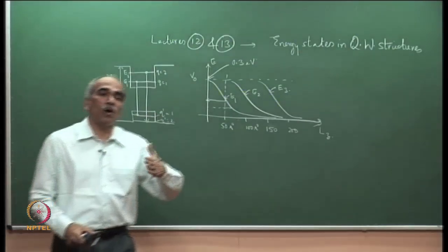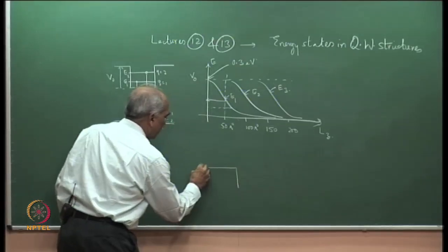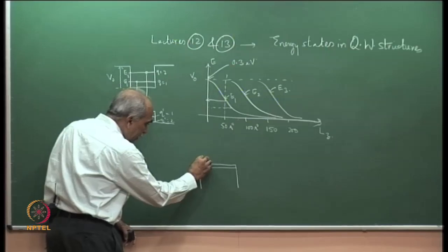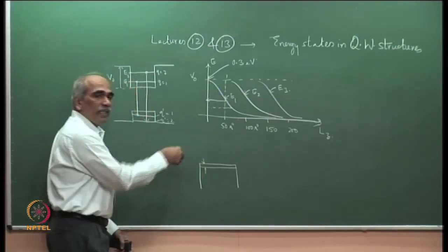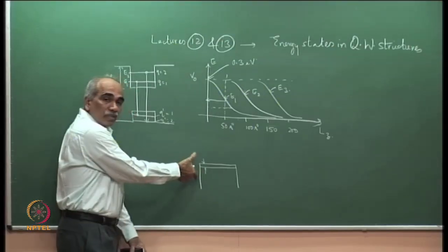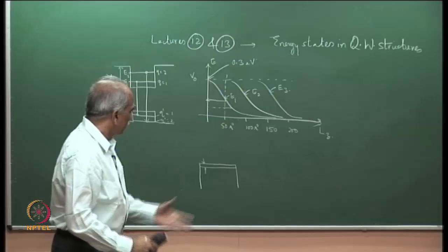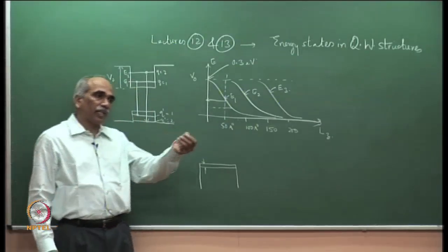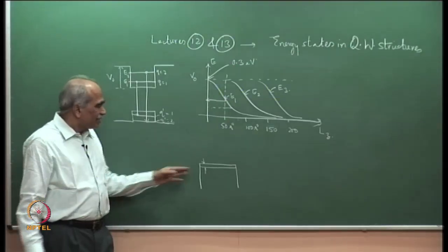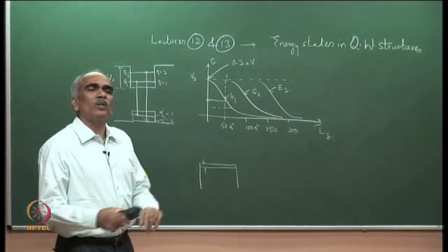If you are depositing a layer by epitaxy on the substrate, changing the thickness is very easy. Simply control the time of deposition, and this can be precisely controlled. In techniques like MBE, we can control the thickness very precisely, correct to one atomic monolayer. But changing the composition is possible, but not convenient.